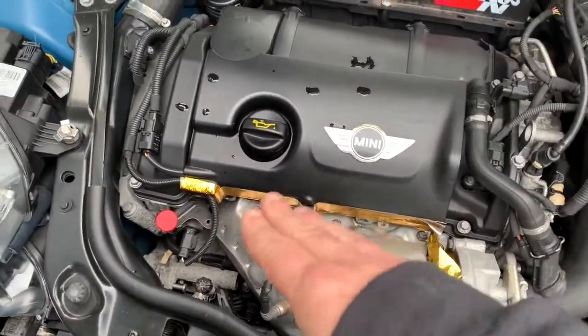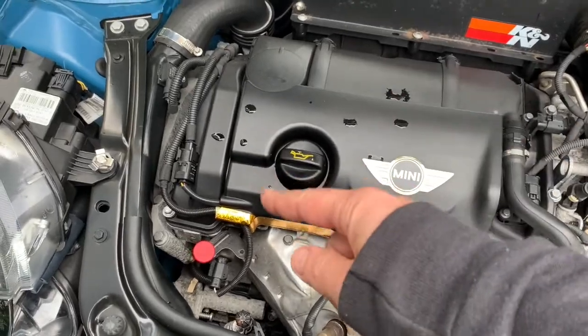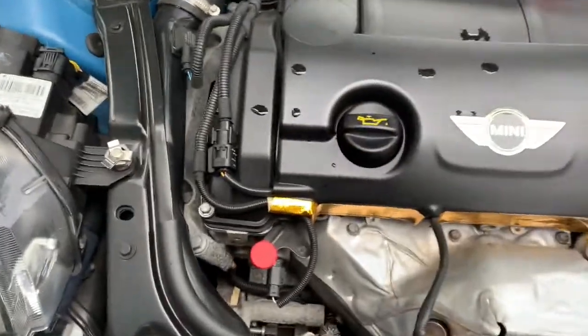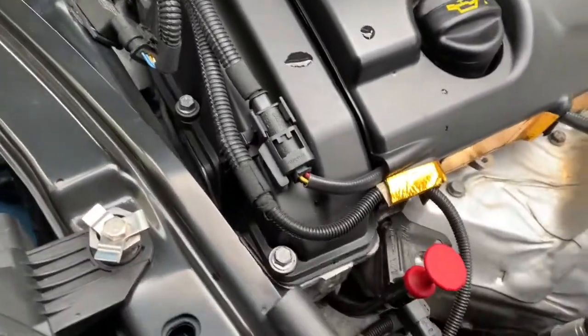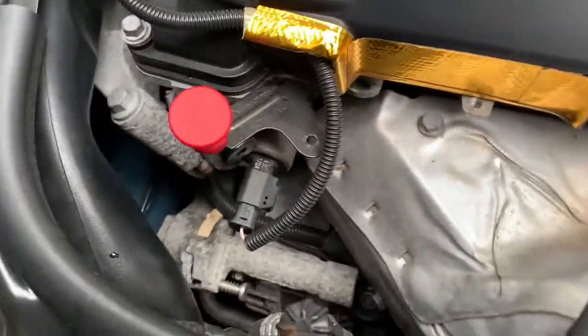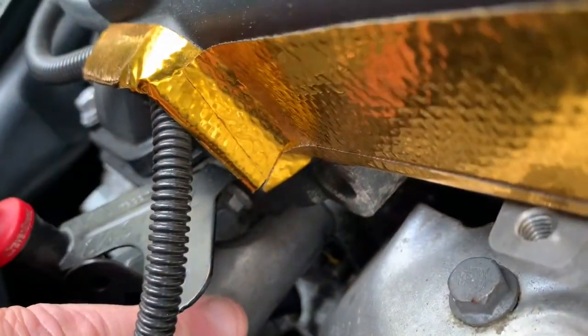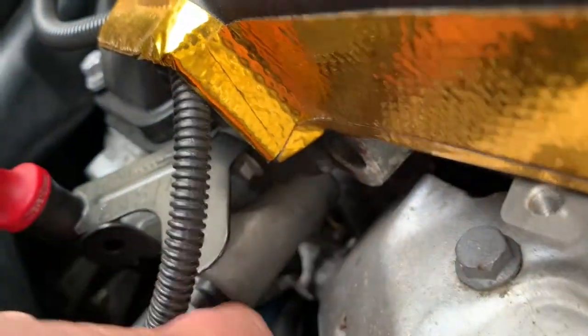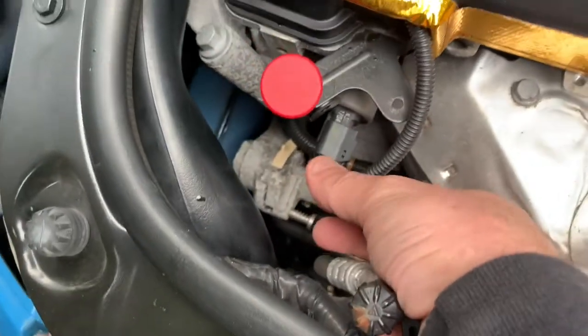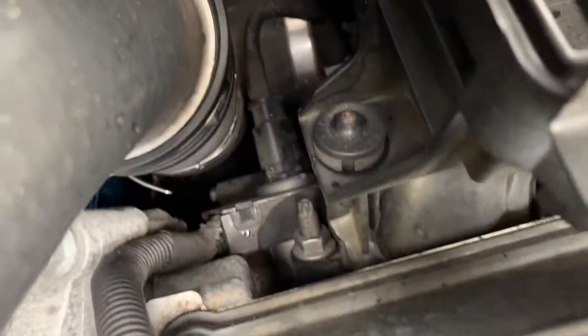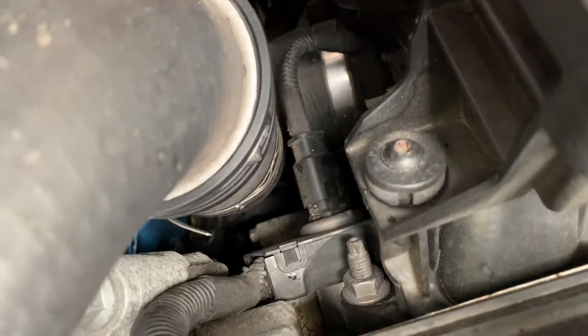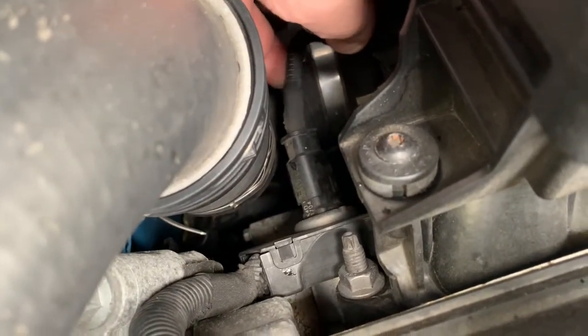Okay, so over here the Mini has 2 variable camshafts. So the oil control solenoids for this guy, there's one here, down here. It's literally a solenoid held in by a bolt. Take the bolt out, you slide the whole solenoid out. It has an electrical connector. There is another one located at the rear. That is this guy right here. That's the other oil control solenoid.